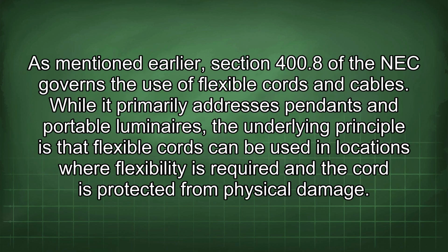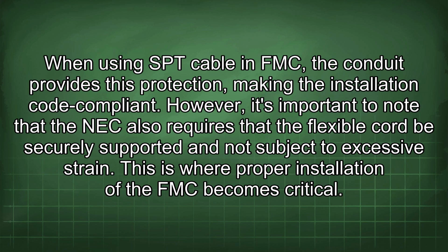Fourthly, let's address the NEC requirements more specifically. As mentioned earlier, Section 400.8 of the NEC governs the use of flexible cords and cables. While it primarily addresses pendants and portable luminaires, the underlying principle is that flexible cords can be used in locations where flexibility is required and the cord is protected from physical damage. When using SPT cable in FMC, the conduit provides this protection, making the installation code compliant.